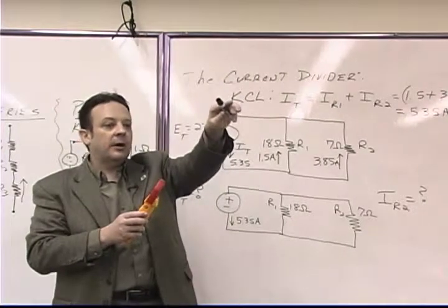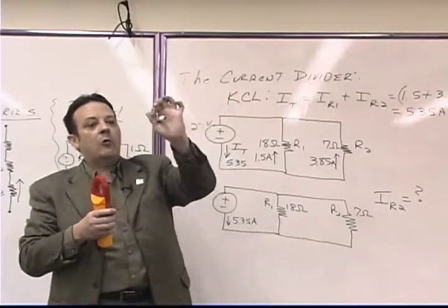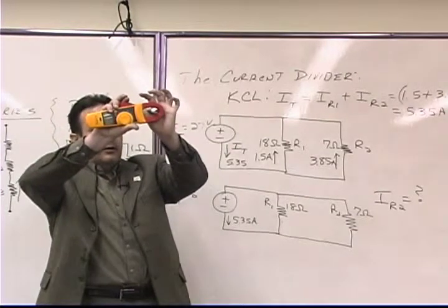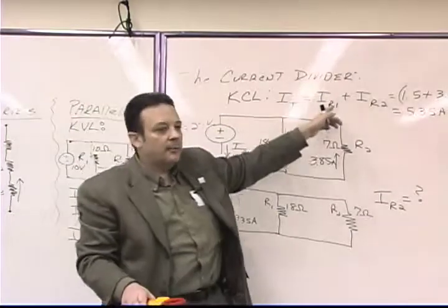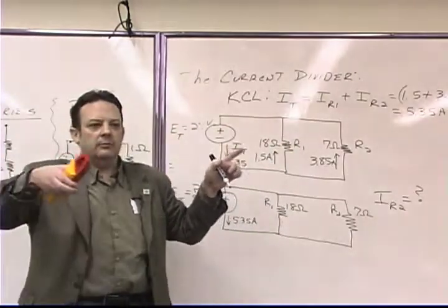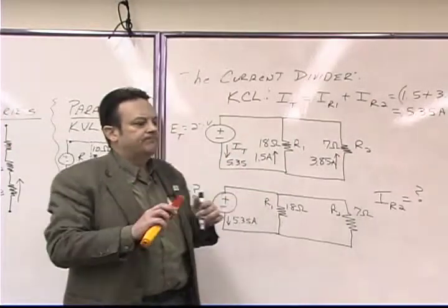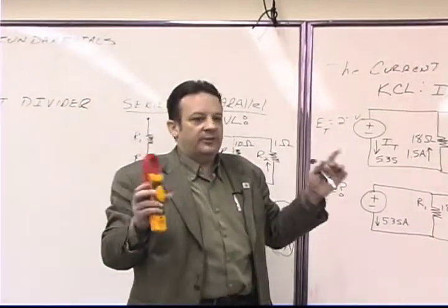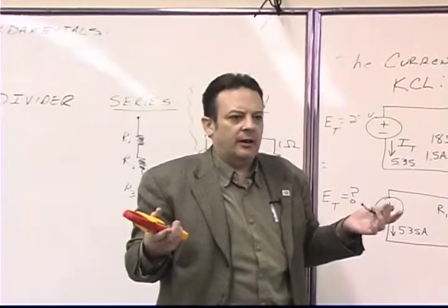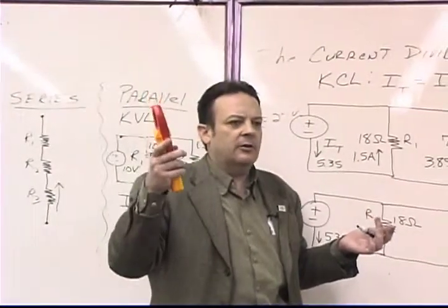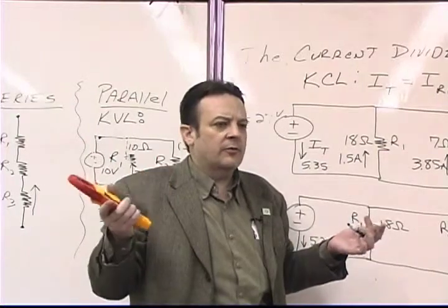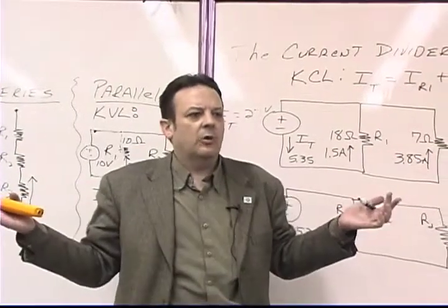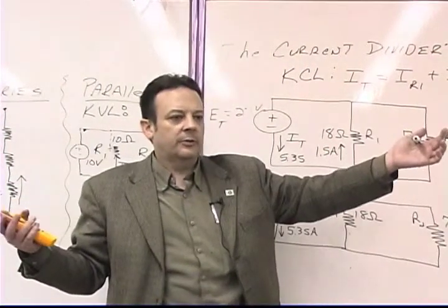Then you go to your main breaker panel and you check the big fat wire coming out of it, and you see how much current is flowing out of it, and that current had better add up to all the currents that you measured throughout your plant, okay? If there's a discrepancy that's more than a couple of percent, there may be a little error in the meter, but otherwise you've either forgotten a load that's in your building somewhere, or somebody's stealing energy from you, okay?